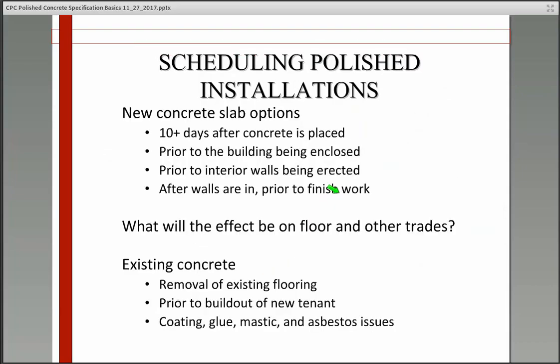Scheduling installations, there's all sorts of different options, anywhere from 10 days after the concrete is placed to after walls are in but prior to finish work. It's important to really talk about those pros and cons once you get the idea of what this project is going to contain and how fast or slow you're trying to build this out. And we can help you with that. Just let us know some of the different parameters, and we can help you understand what will be the effects on the floor with the other trades and by doing it at different times.